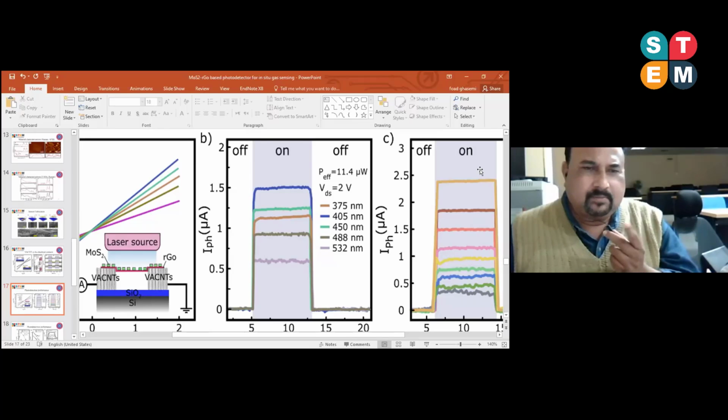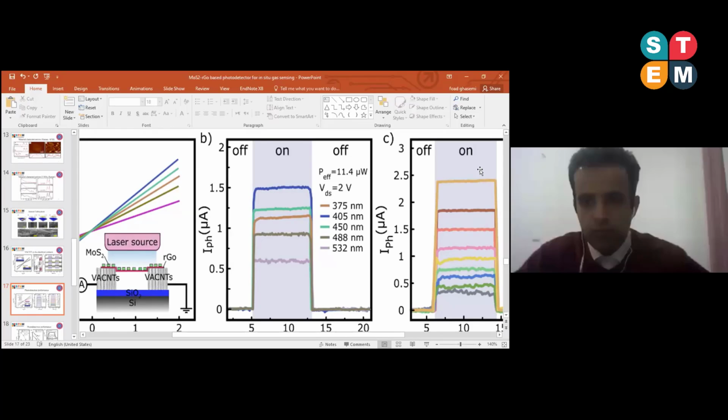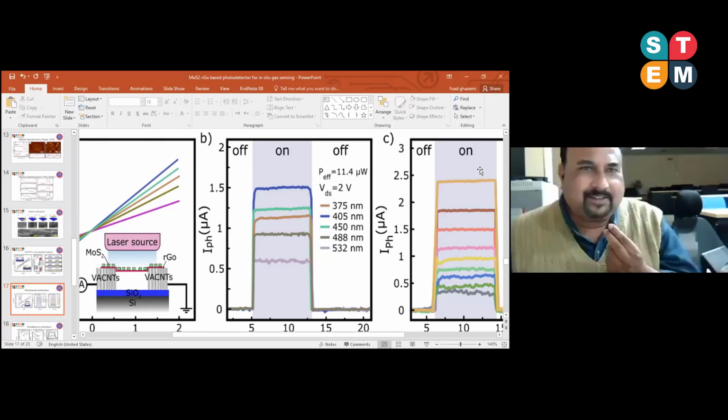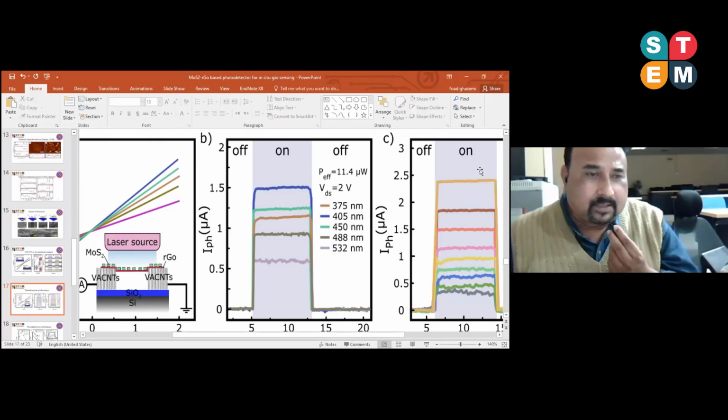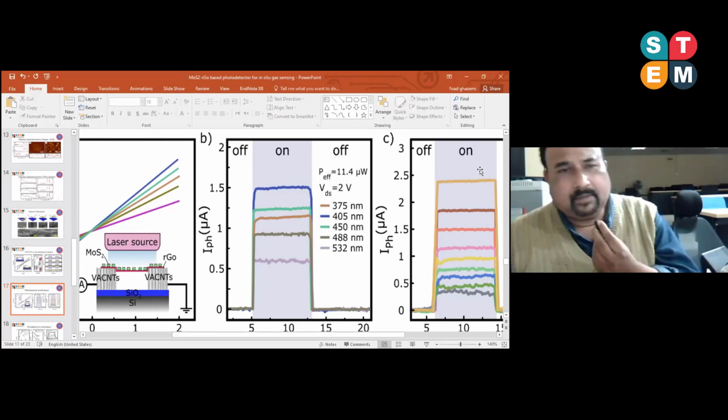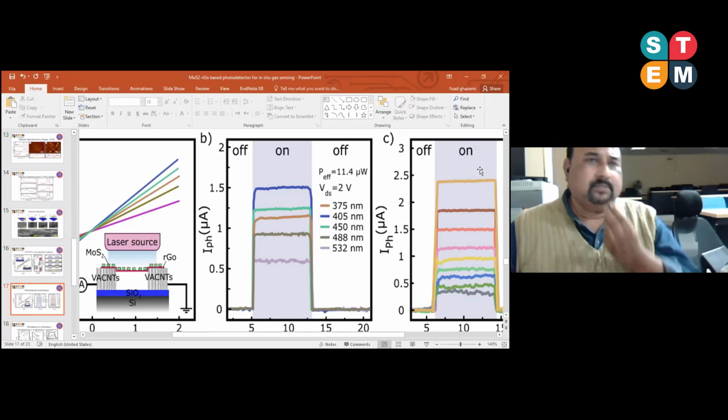Another question, because I am curious: your current is very small, a microampere, right? Yes. And microampere current is always suppressed by external noise, because noise is always higher in the laboratory. No, we also have some sensors where we can easily measure nanoampere current. So for that, are you using a lock-in amplifier or some other gadgets for amplification and rectifying the inherent noise of the system for the measurement?